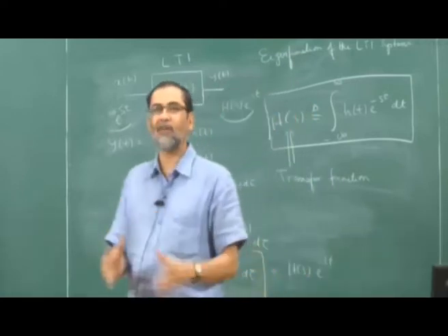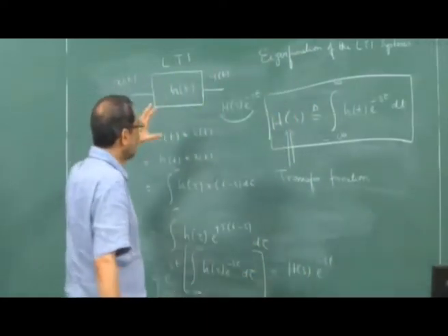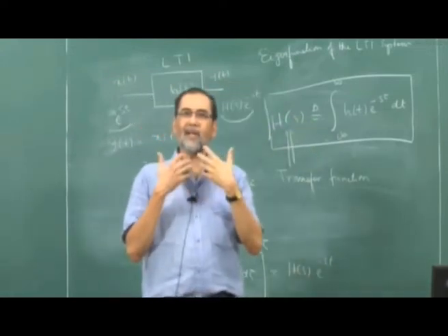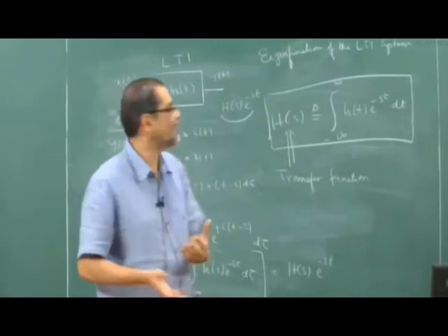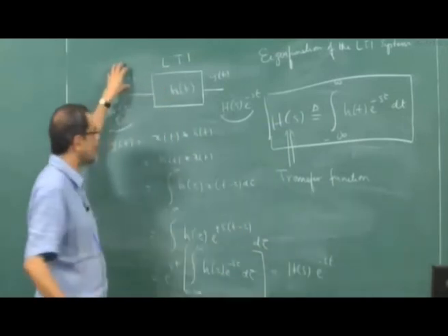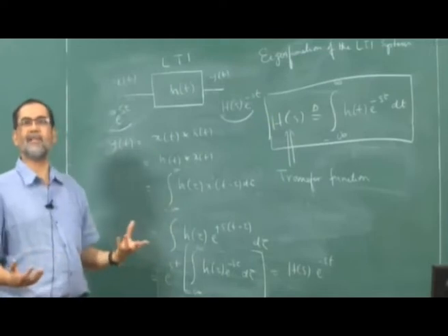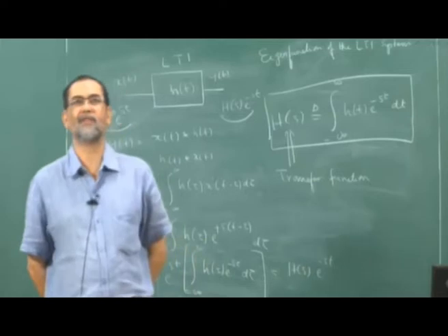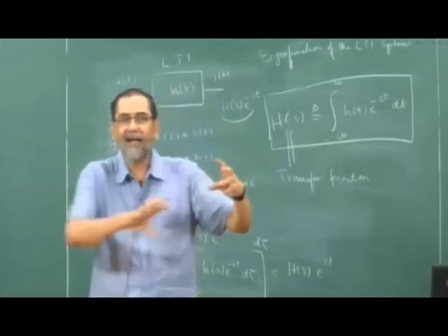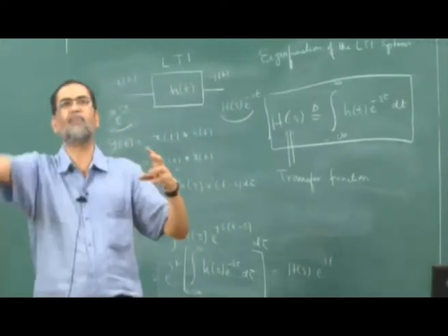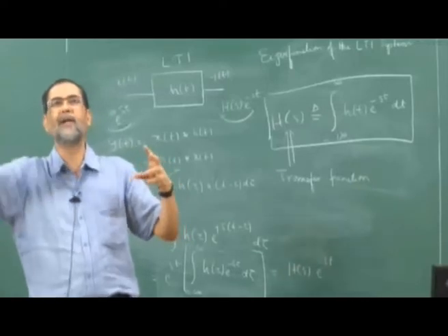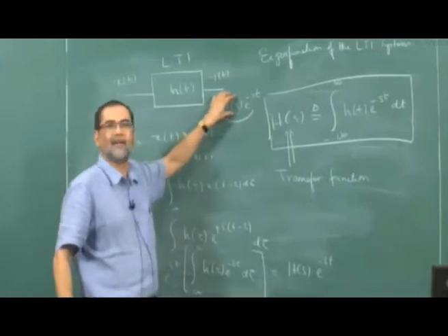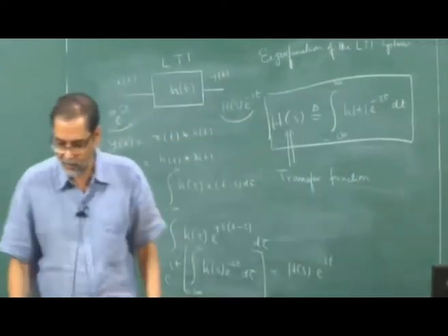And the motivation for that is this eigenfunction analysis, right? The reason I want to go into the frequency domain is I want to express my input signal in terms of its frequencies, because the moment I do, I can take individual frequencies, give them to the input, and predict the output will be the same frequency with some different scaling factor.